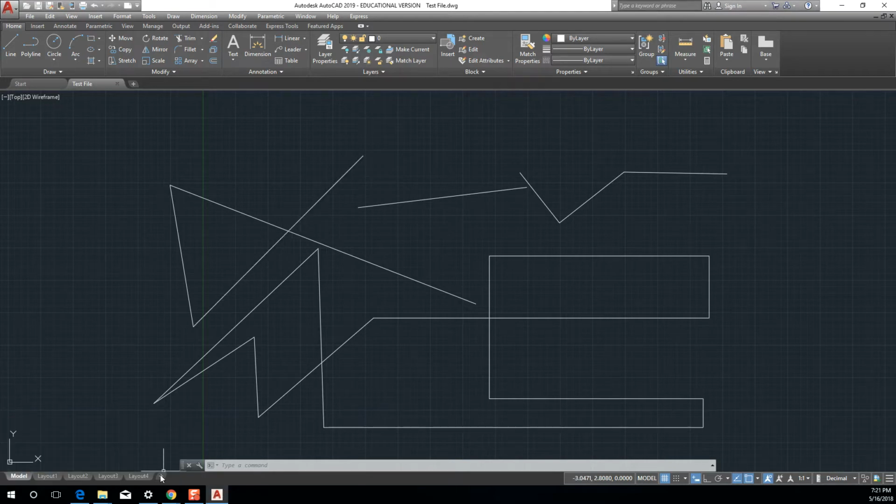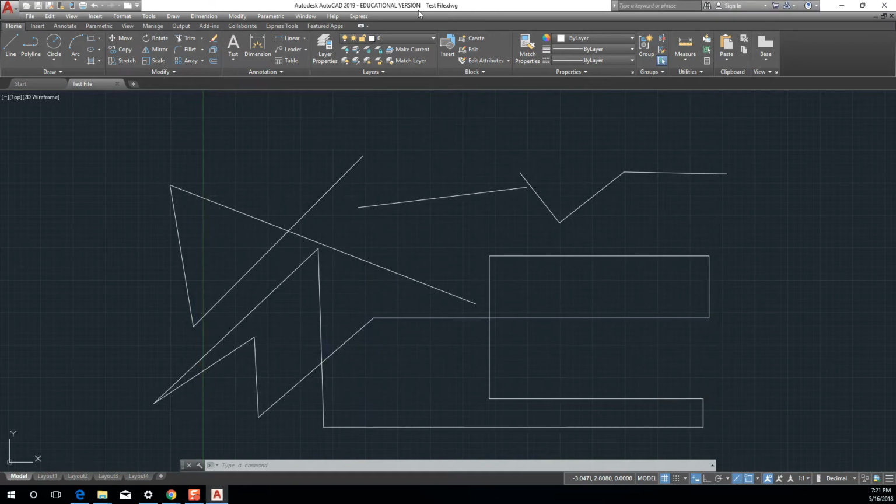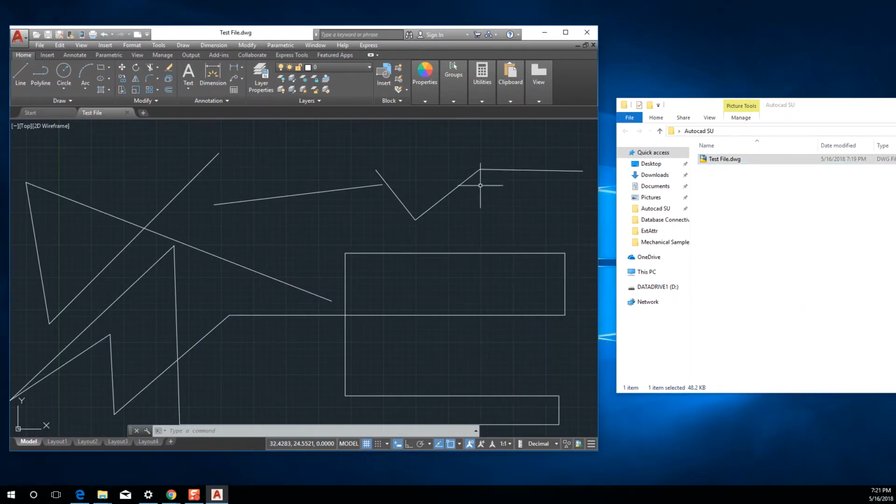But I have to say, and let me show you. So now I have my working file. Let me hit in my AutoCAD file here, Control S. And my backup file is regenerating. So I just deleted my working file, renamed my backup, right? Which turned it into a working file, opened it, saved it, and it created another backup, okay?